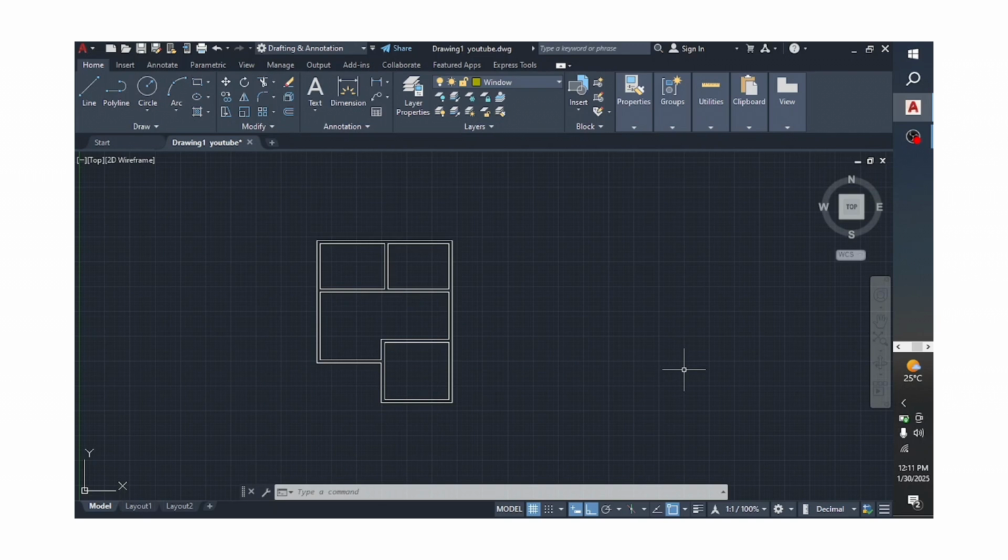So I want to draw to show the windows on the plan. They need to be rectangular with the width equal to the wall. So meaning we are going to use a wall of a width of 200, and I'm just going to make windows of, the windows will be 1500 by 1500, but that you'll only see in the elevation. For the plan, I'm just going to give the length and the width of the wall. So I'm going to draw them using this rectangular tool.